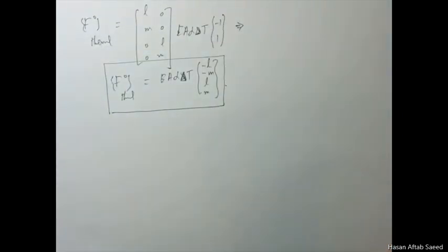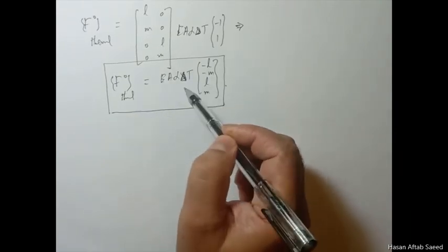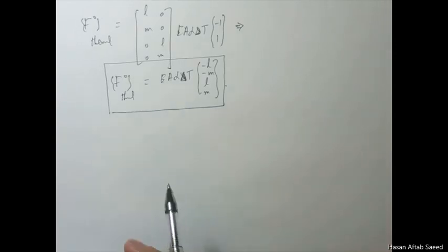For thermal vectors, if any temperature changes are there, you apply this in the global coordinate system. Then you assemble all the elements into one whole system. You get the system matrices. Then you apply any concentrated loads acting on the body at the end.